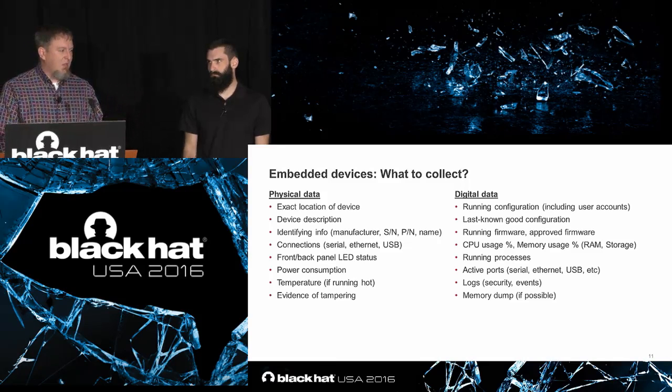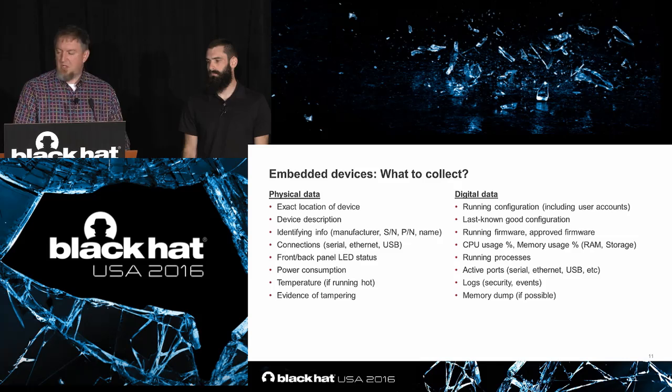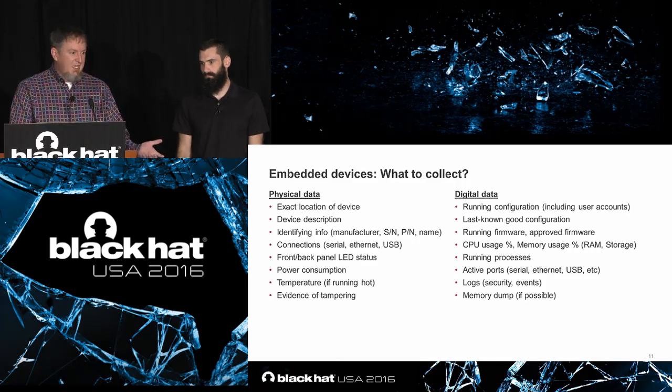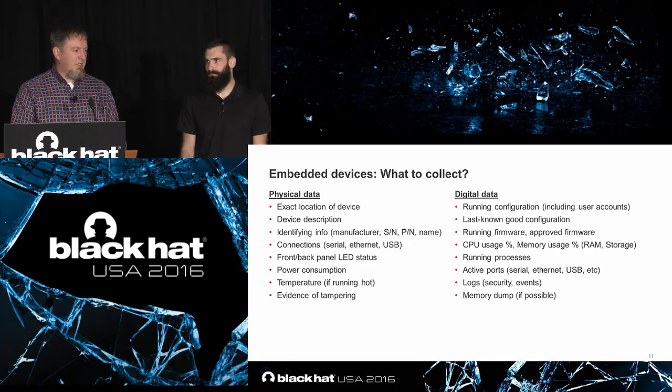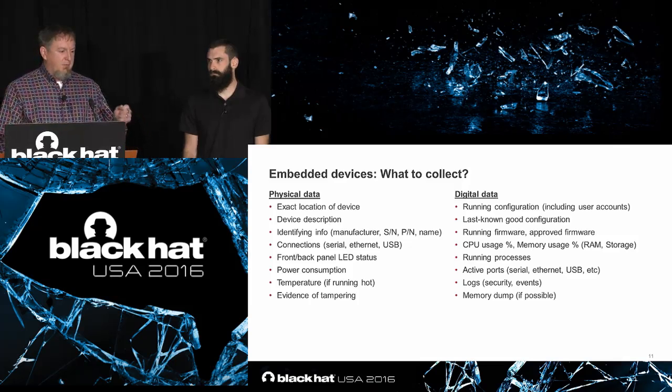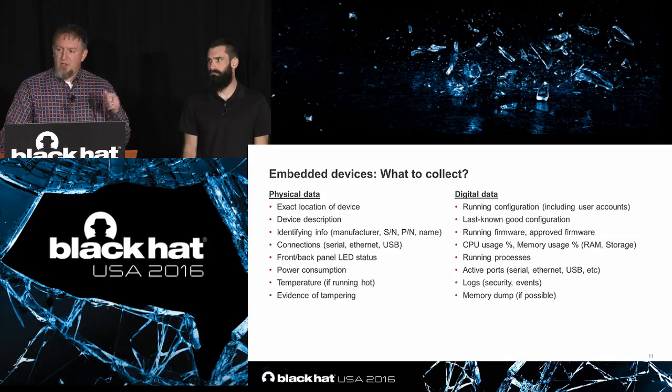Physical data is like the exact location of the device, which substation or what platform out in the Gulf of Mexico, you've got an old platform, or what breaker cabinet it might be in, device description, serial number, part number. What are the LEDs? Whenever I got a call and there was a problem in a substation, send the technician out and say, well, what do the lights say on the front? Are they red and blinking, or are they all green and acting normal? See what the power consumption is. Temperature.